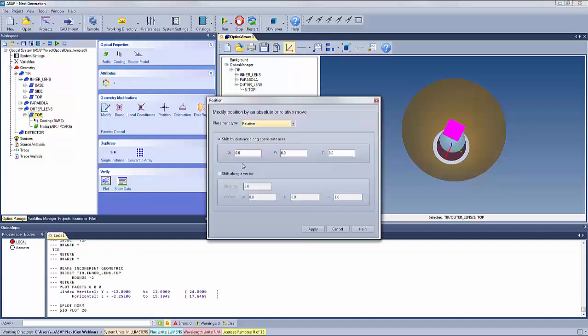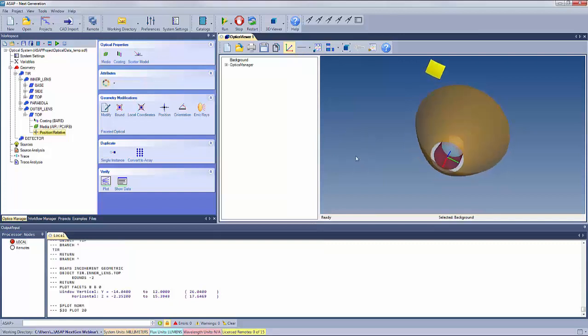And this is going to be a relative shift, and we're going to have basically 6 by 6 elements, or 7 depending upon whether you use the original component itself. So we'll move this component into space where it's supposed to be, so when it's replicated, it will be replicated across the face of our geometry, and there it is right there.